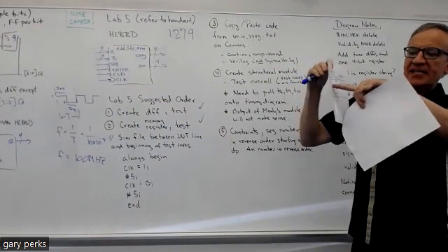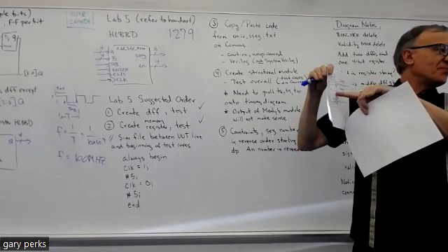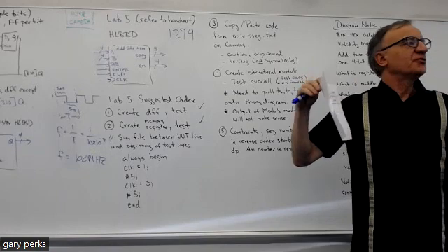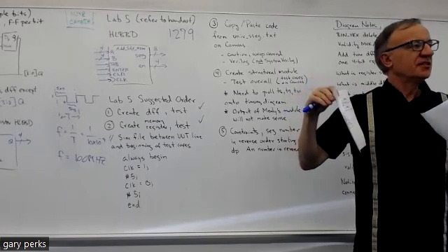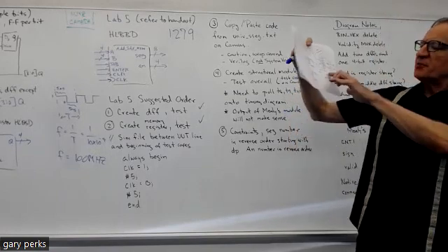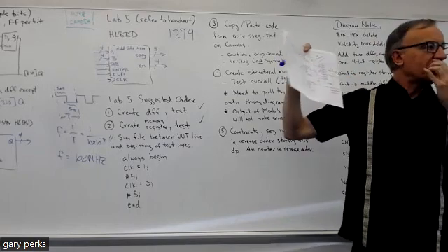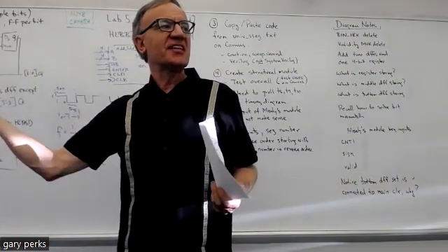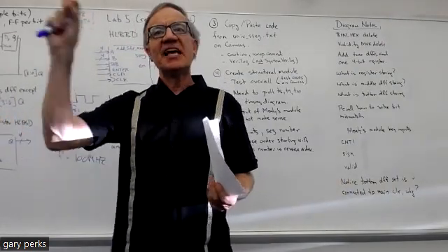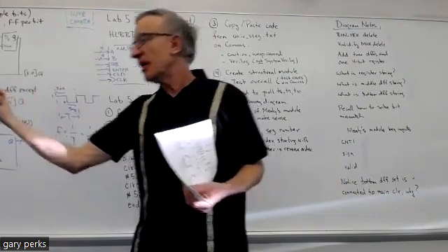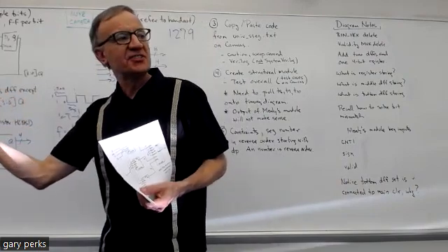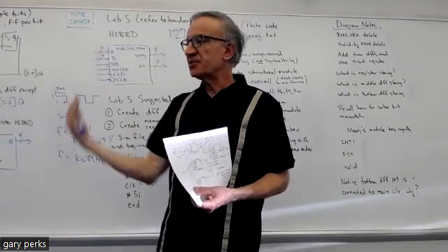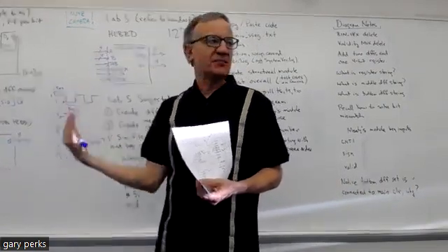Yeah, you still need this AND gate because it's going to generate that output only when it's valid and negative. That's when it will generate a 1. Because the way Mealy's module works is that if the sign bit is a 1, it's gonna light up a dash on the furthest to the left 7-segment display. So instead of an LED lighting to show it's negative, you're actually gonna see a dash on the furthest to the left 7-segment display. And then your result will be on the furthest to the right display.